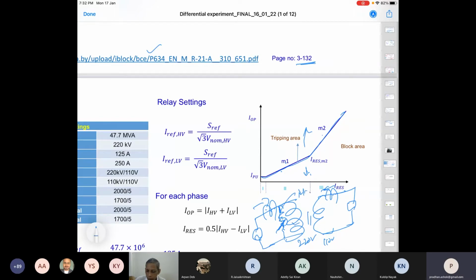And now for anything external, you put more resistance and control it, and make a short circuit kind of thing also, lower and lower. Then these are nothing but external to this. So beyond these two CTs is external, inside these two CTs is internal.